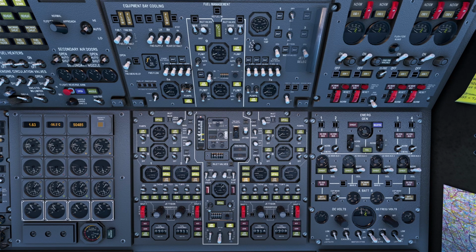Stop the pumps first, close the inlet valves, and open another route. I don't really care in which tank it goes, because they automatically feed in both of them. And by turning on the pumps again, fuel, you see, is rising. It's automatically pumped to the right side.